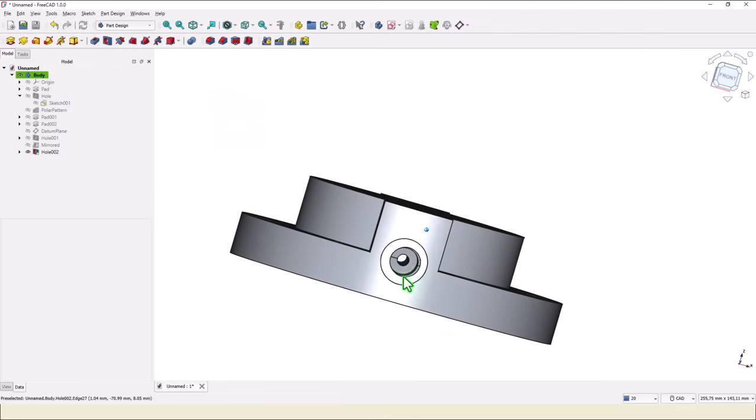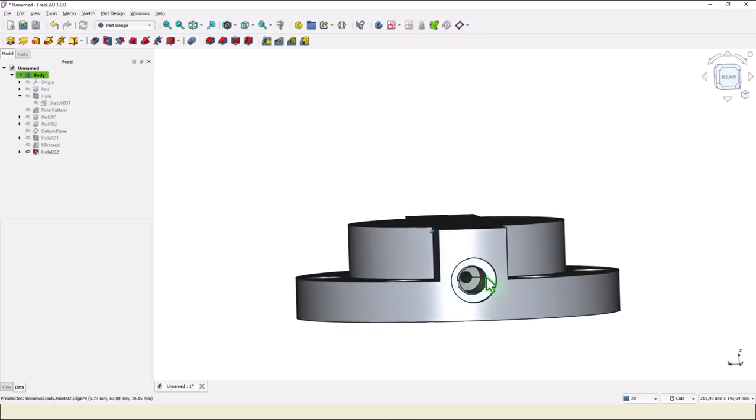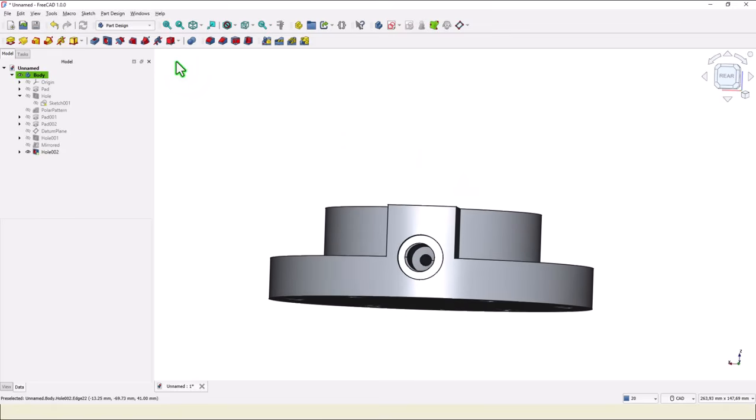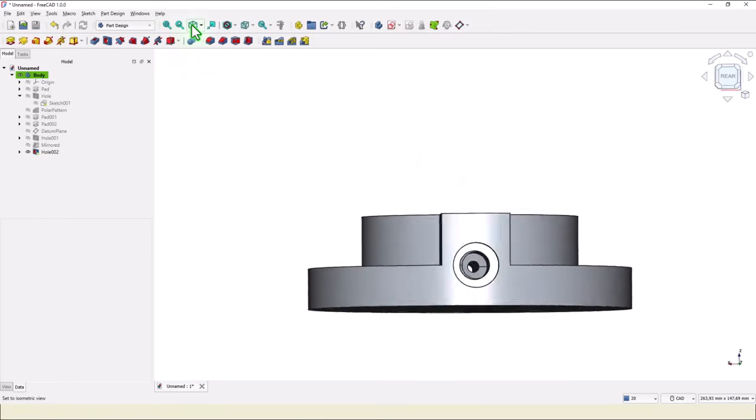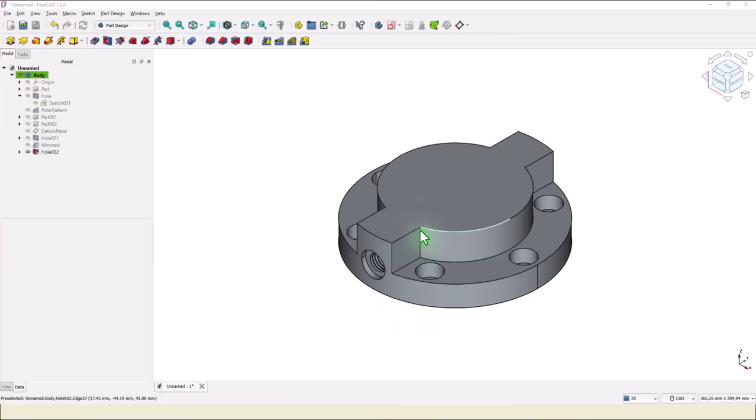Now you see this to the other end. Good. We don't want to forget these fillets of radius 8 to each of the 4 corners. We select this edge, if we can.